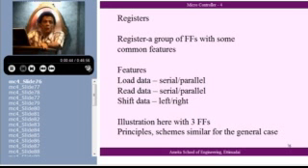So the second set is what is called a set of registers. We combine flip-flops in a different fashion to form what is called a register. A register is basically a set of flip-flops connected in a particular pattern, just like a counter, but in a slightly different form. How you look at it: in a counter you look at it as a counter. In a register, you look at it as something where I can store a number, I can erase the number, I can change the number, I can shift the number, one side, other side. All these things I do with a register.